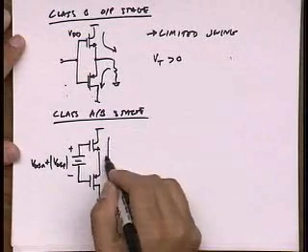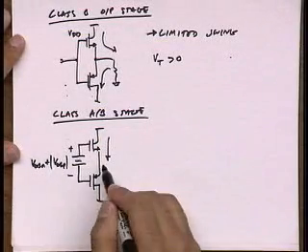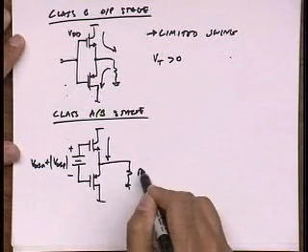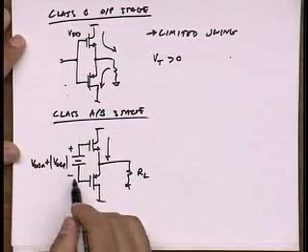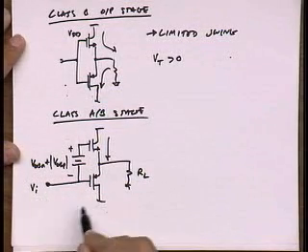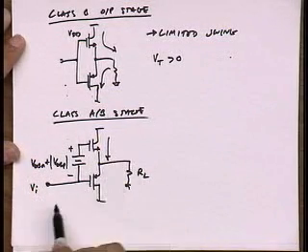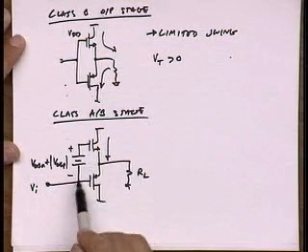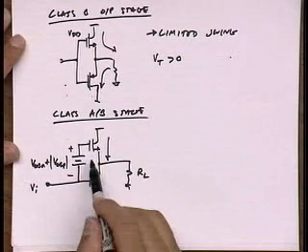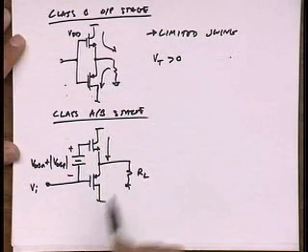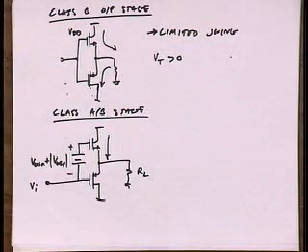And that runs against some trickle current, and then the actual load current can go much higher. That's why it's a class AB stage: if I make the input much larger, the VGS of this device can be sufficiently large to turn it on even harder and deliver more current, and so on and so forth.